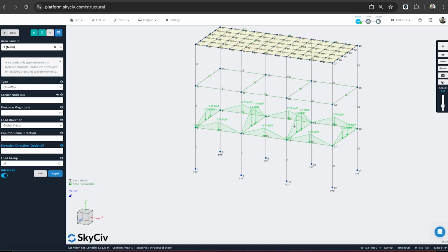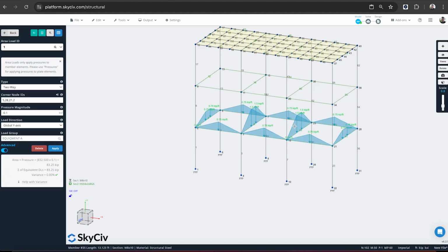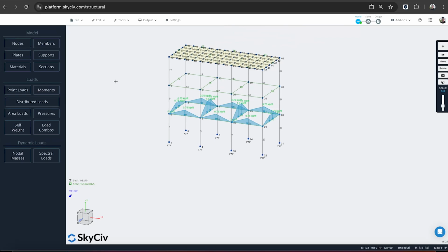These calculations can be quite difficult or time consuming to perform. So this is a really great feature to easily calculate those, and with confidence, where you've got some variance checks to make sure that all the force is being applied to your frame correctly. We also do column wind loads, which allows you to add variance to your pressure, so you can start from one value to another. Open structure loads, and then non-rectangular loads, which might be more complicated shapes that you want to apply a load to. So that's really helpful.